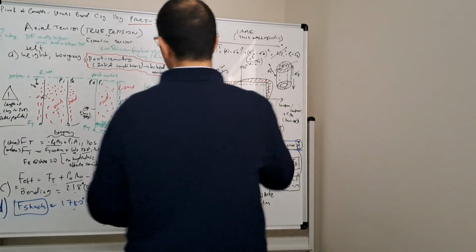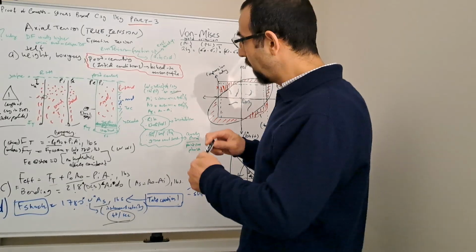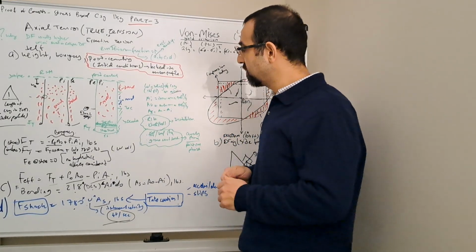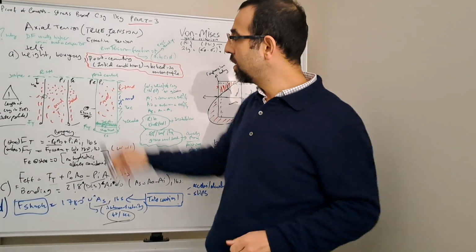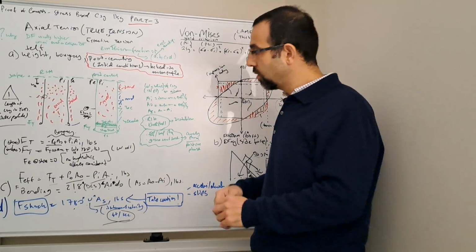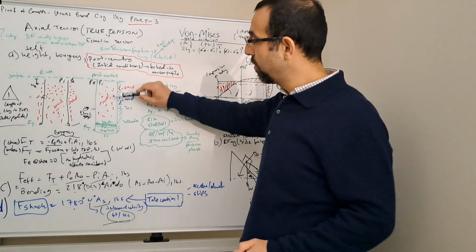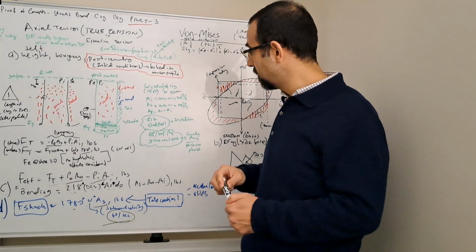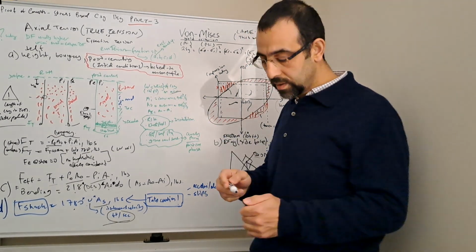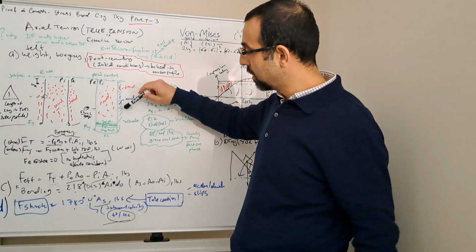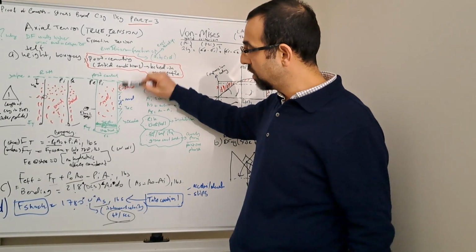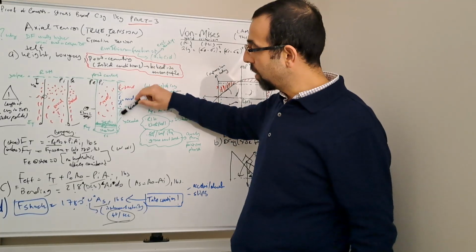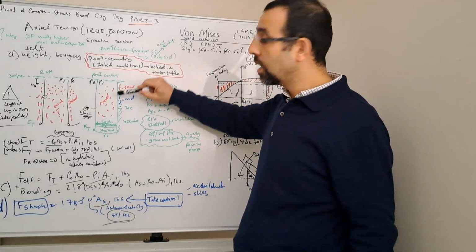So before we move from this page, a couple more things to discuss here. We talk about running in hole. Let's say we run in hole, and then we pump our cement, and we have an FCP, which is the final circulating pressure. That is due to the hydrostatic difference between the cement, spacer and the mud, plus some friction.